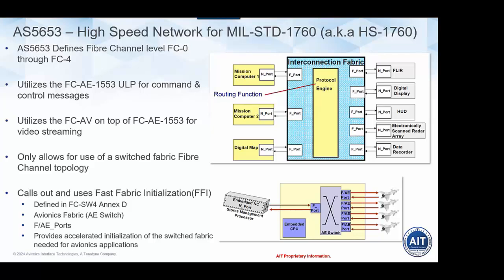AS5653 also calls out something called fast fabric initialization, or FFI. FFI was actually defined as an annex to one of the Fibre Channel standards, specifically FC-SW-4. That's one of the Fibre Channel switching standards. And that specifically defines what's called an avionics fabric, or an AE switch. And what's unique about an AE switch and its utilization of FFI is that it provides for accelerated and really fast initialization of the switch.